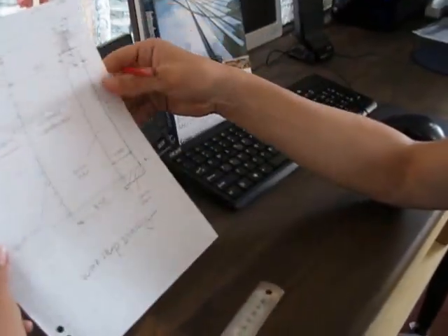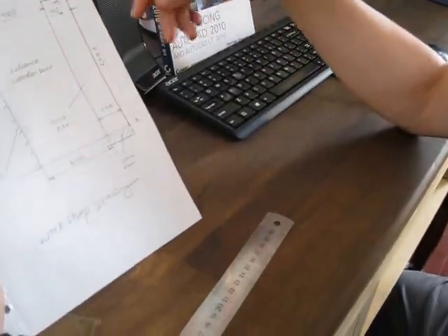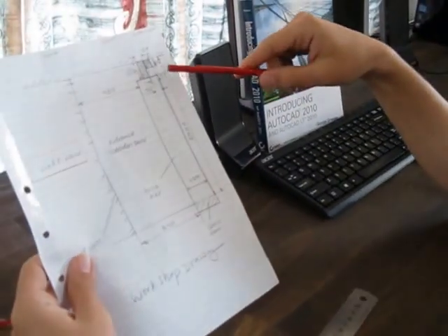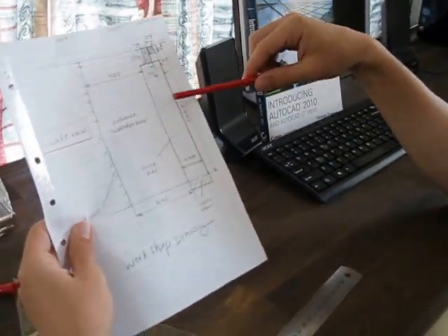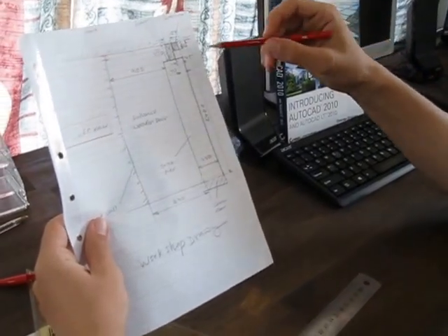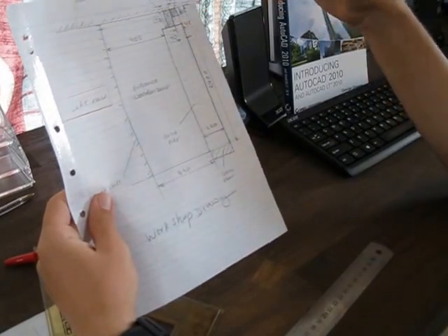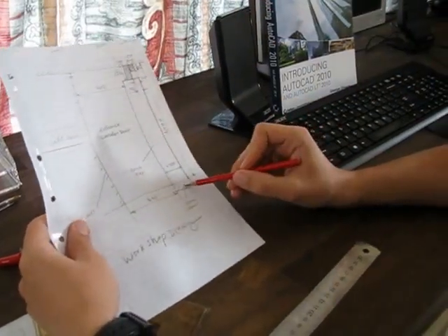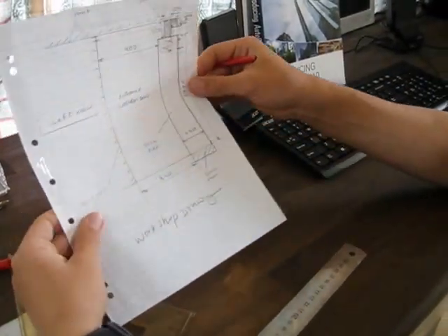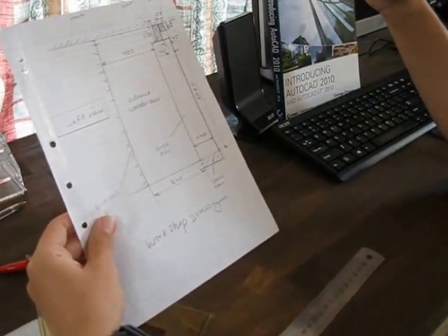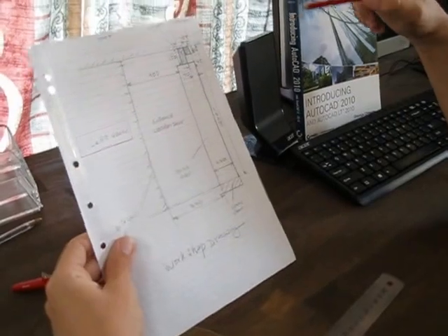So this is the left view of the workshop. Which pier has failed? So we have this pier. What has happened to it? So we need to replace that. Why? Because of the support. Because there is a crack at the bottom. The crack is almost here. So the crack is here, and the pier has gone down into the ground a little bit, and the cracks are up here. It's not safe. Yes. Right.